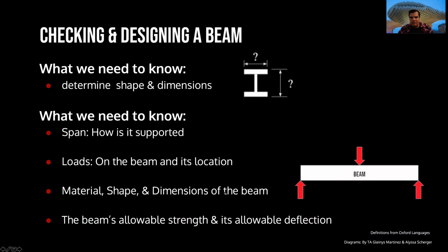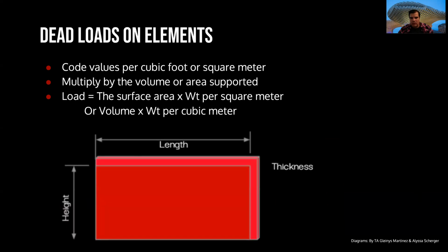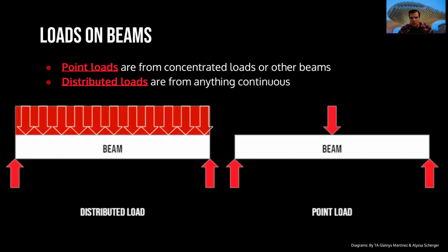In that case, we have the loads that the beam had, and in that way, we can understand that the loads will be supported by the reactions. And we already know that there are 2 types of loads. One is a point load, the one that we look at here on the left side, which is just at a point, and the other is a distributed load. Distributed loads are like many point loads together, one after the other. It's like you have books, one next to the other, and every book has pages, and every page has a weight, and if you move a little bit to the left or to the right, you have additional pages, which means additional weight.